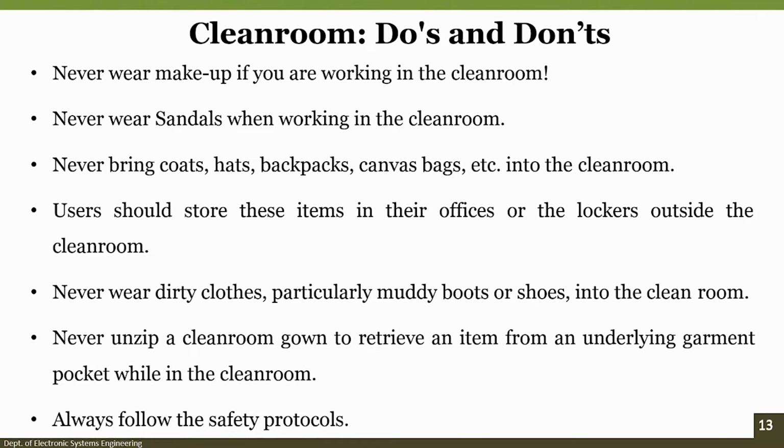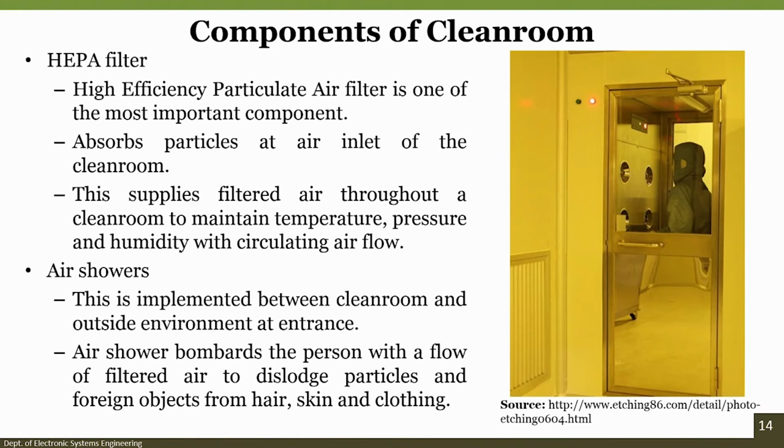You are not allowed to bring coats, hats, backpacks, or bags; all these items should be stored in the office or the lockers outside the clean room. You cannot wear dirty clothes, particularly muddy boots or shoes. Never unzip a clean room gown to retrieve an item from the underlying garment. Always follow the lab protocol, and safety is very important.